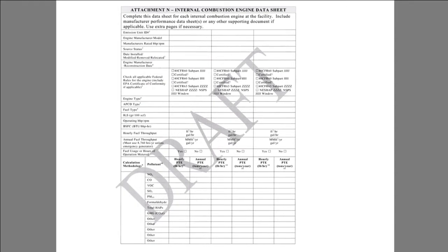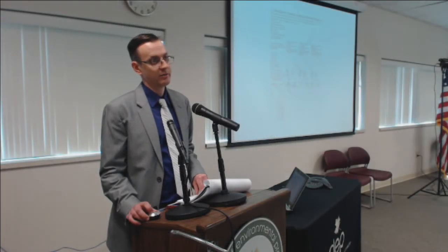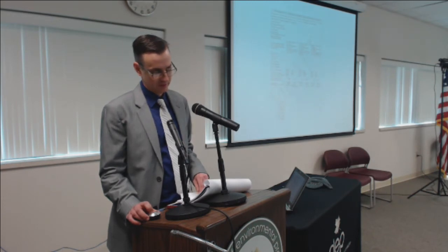Also, you want to indicate is the fuel usage or the hours of operation metered, yes or no? And then you indicate what your emissions are and your calculation methodology. When you calculate your emissions, you need to use manufacturer's data. So please utilize manufacturer's data when you do your engine calculations.